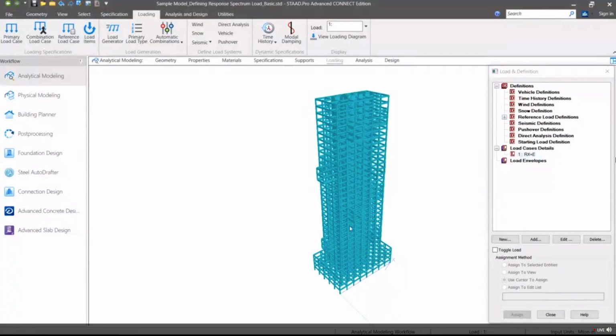So IE by R value in either direction comes as 0.28. We need to specify this value as direction factor in both X and Z direction. We will consider only positive factor as negative directional load will be considered in the load combination cases.